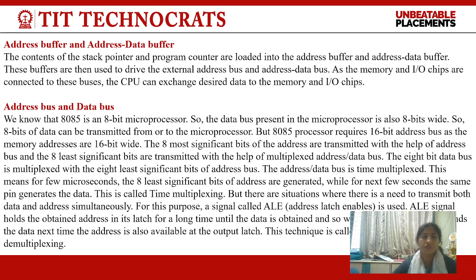Now, address and data buffer, as we have already discussed, the 16-bit address buffer and 8-bit data buffer. So the least significant 8 bits of the address bus are multiplexed with the data buffer, and using the ALE signal, they are demultiplexed from each other.